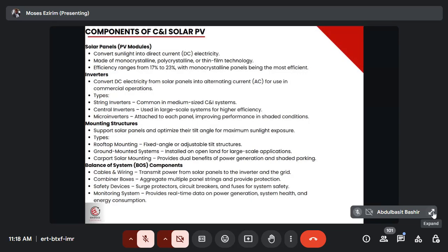So the reason why we put that breaker is simply because if an excess current that will damage that equipment wants to pass through, that breaker will trip. It will not allow it to pass through. All right. Now, if you use a 5 amps breaker instead of 40 amps, what will happen? It will trip. It will keep tripping. And if it keeps tripping, that means that current will not flow.